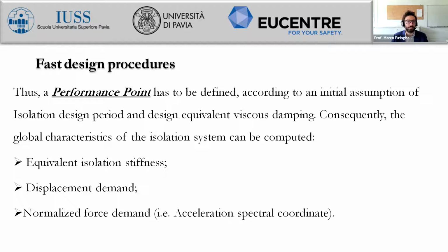and the numerical values of the equivalent viscous damping ratio are directly related to the typology of isolators that we are going to install. We have seen that for rubber bearings we have two typologies of isolators, low damping and high damping.